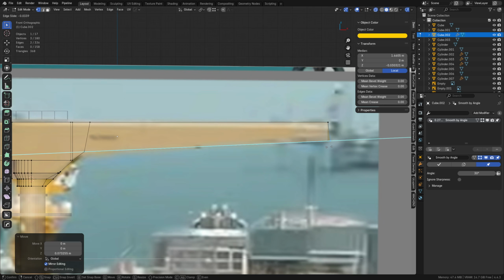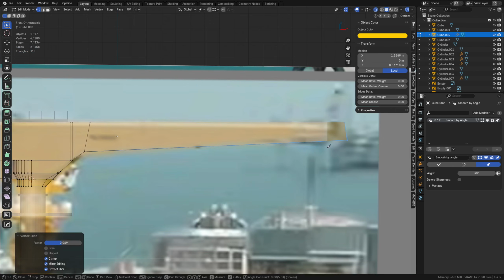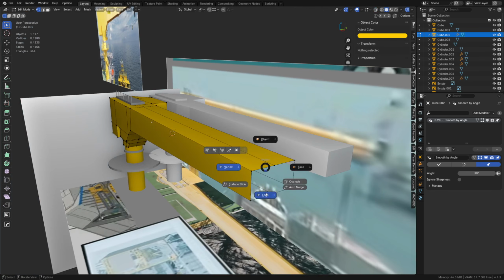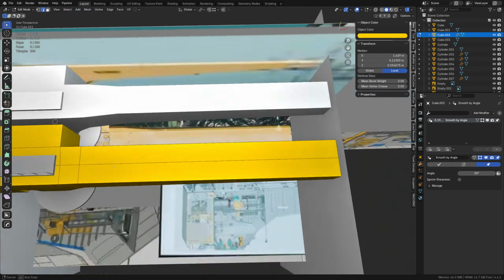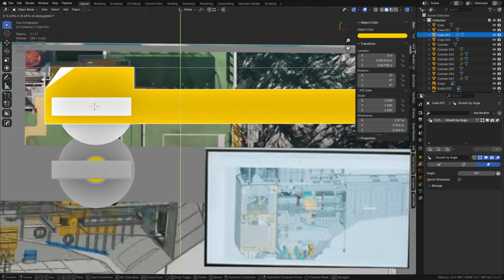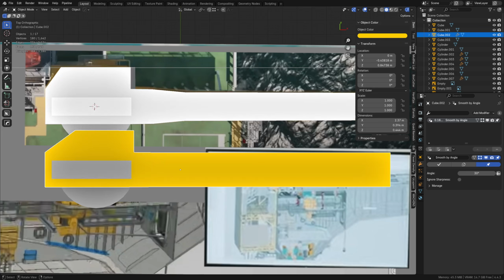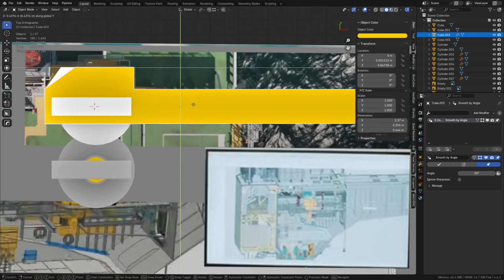G twice, hold Alt. You can overextend these with GG twice, hold Alt, and then you can do a cut, maybe like KCA. Boom. You can just cut off the tip. Boom. Press F. All right. I don't think we matched our shape here very well. Yeah, we didn't squeeze it. So I'm going to copy the Y value here so I don't have to come back for it. I'm just going to paste it back in.